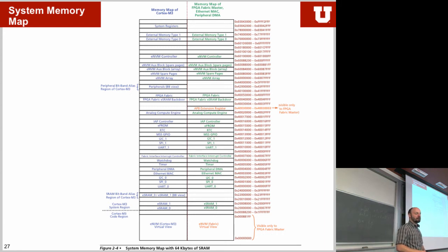Right? So what is all this here? It looks like a lot of memory that's just sitting out there. Lots of peripherals. And that's exactly what's called memory mapped I/O. So this is all digital logic that sits behind these things here. It's not normal memory. Well, not entirely true: up here there is some more memory. But these are all peripherals. This is all digital logic that sits behind these memory locations. And that's what memory mapped I/O is all about.